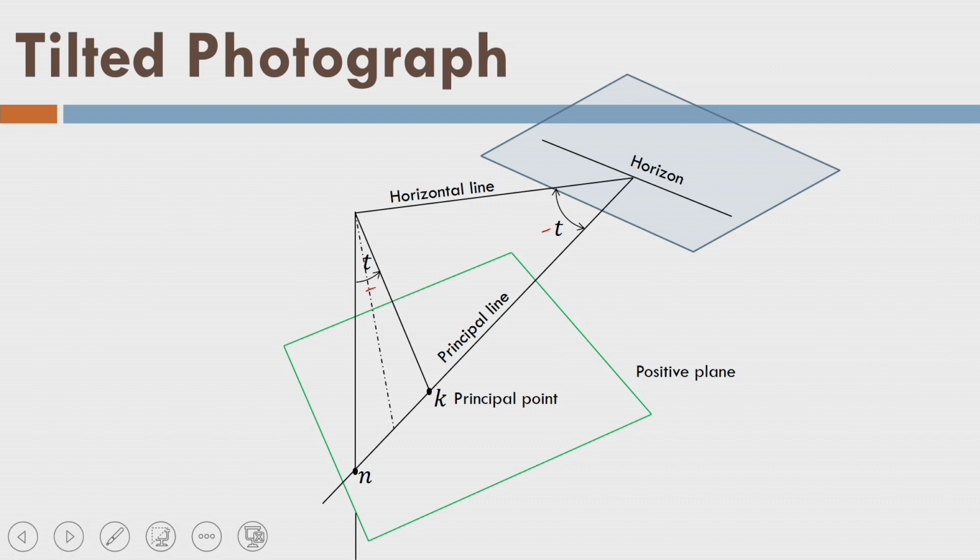I am showing like this. So, this is my optical axis by finger and the pen is showing the plumb line. So, this is my tilt angle here. You can see here tilt angle. So, that is shown in the animation. Now, if I bisect the tilt angle by a line as shown in the animation, it will intersect at point I, and this point I is called the isocenter of the image.